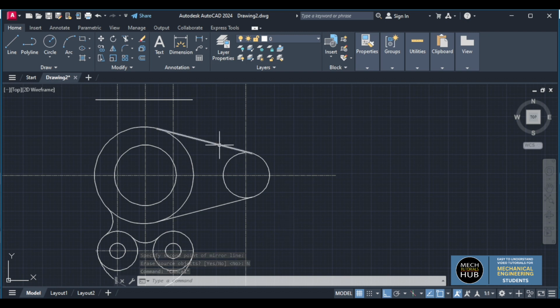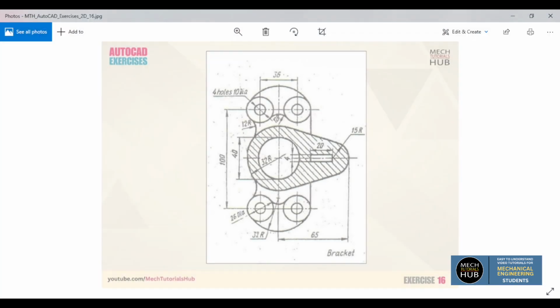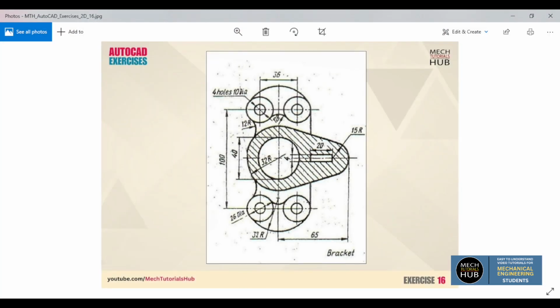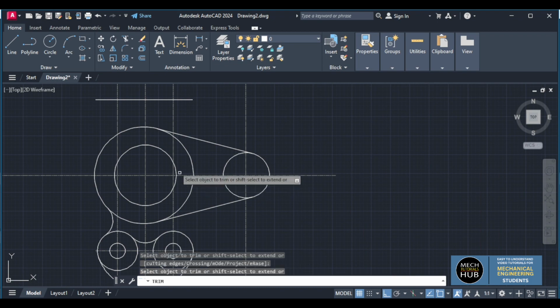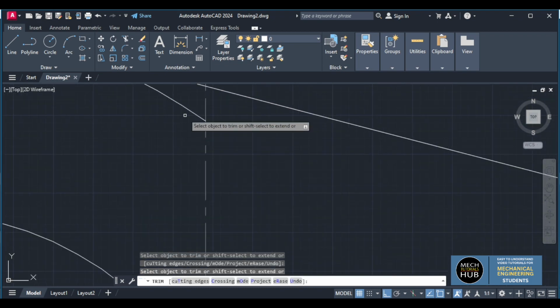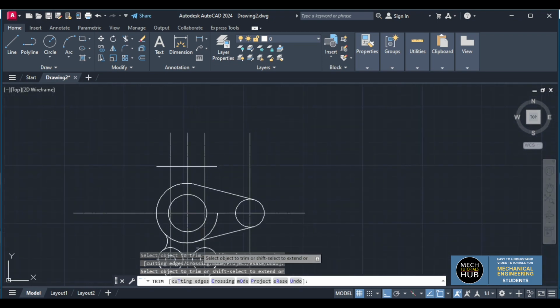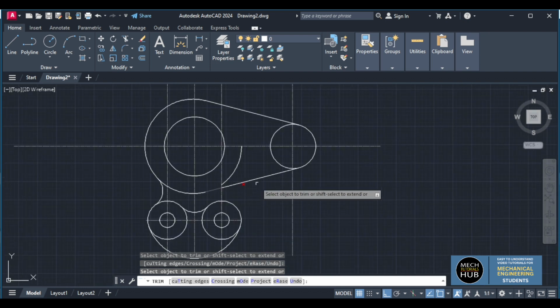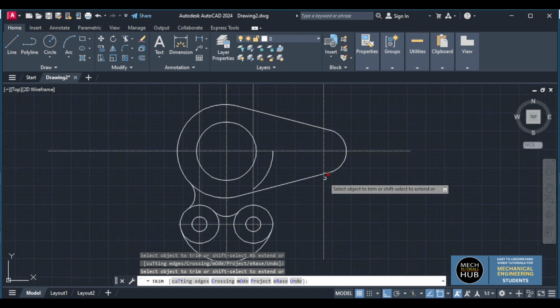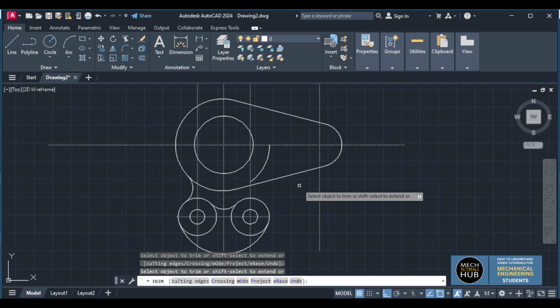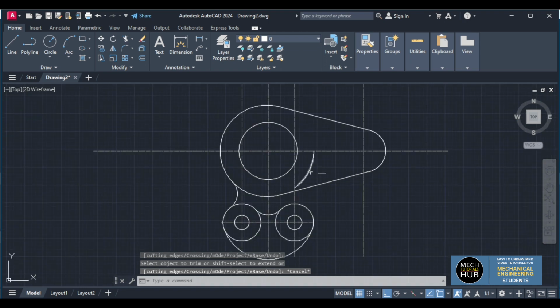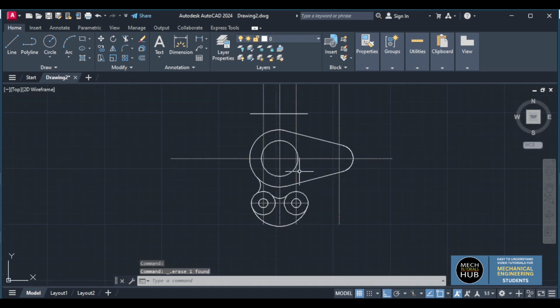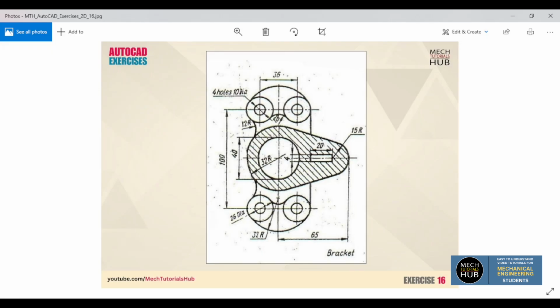Okay, I can repeat the same task on the other side also, but I am not doing it. Okay, then I go with trimming the unwanted portion. TR double enter. This is not required. This part and the bottom. Similarly, this one. Internally some portion is left. Zoom out completely, make it big and see which is not required. This is completely unwanted, I just delete it. This is how the shape looks like, followed by a rectangle 20 by 4.